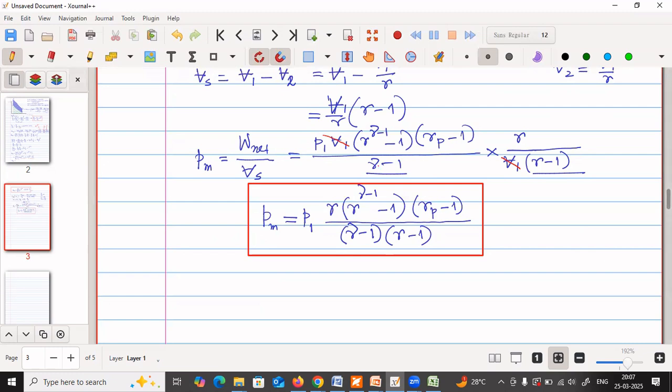So the thermal efficiency of the Otto cycle is equal to 1 minus 1 by R to the power gamma minus 1. As you know the compression ratio and the fluid, you can calculate this efficiency within one step. So that can be 3 marks maximum. Now if it is work calculation, then it requires a longer process, so it will take time.